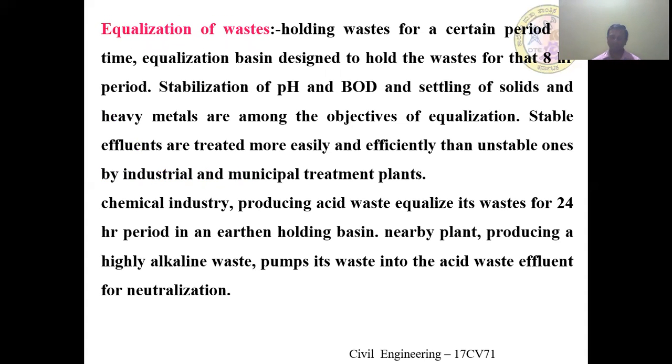Then equalization. This is one of the methods where we are going to use equalization, which is the best part. Holding waste for a certain period of time, equalization is designed to hold the waste for an 8 hour period. During that time, stabilization of pH, BOD, and settling of solids and other heavy metals are among the objectives of equalization.